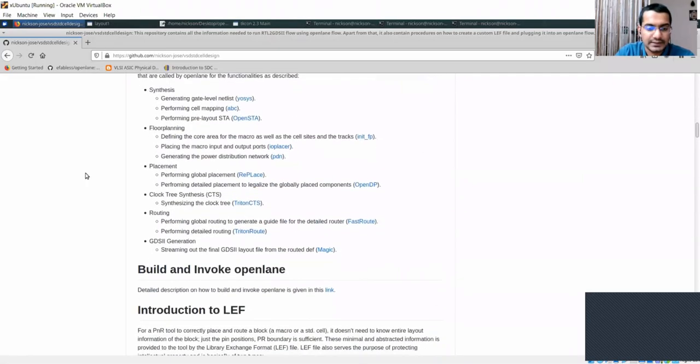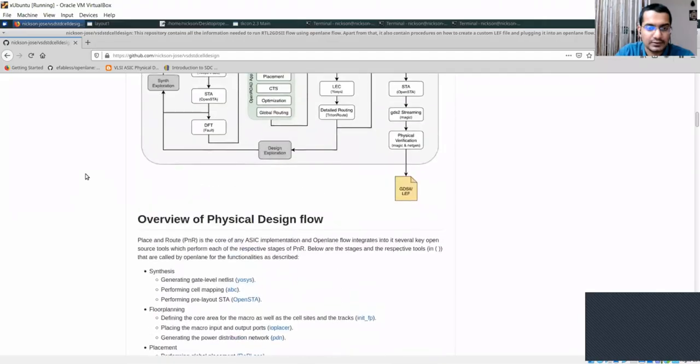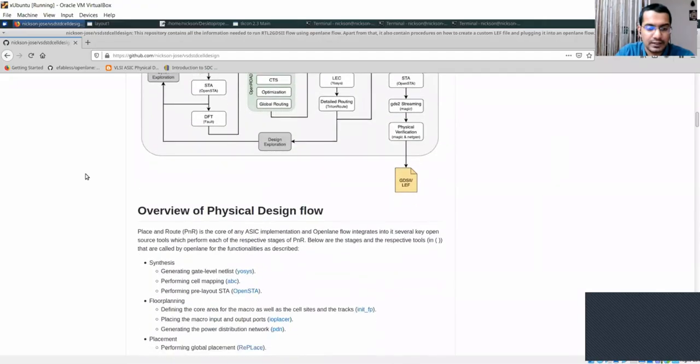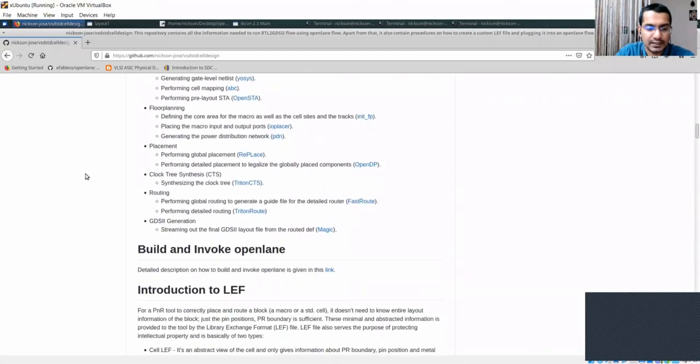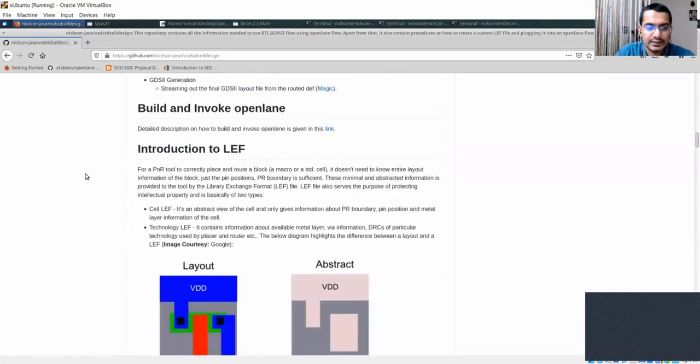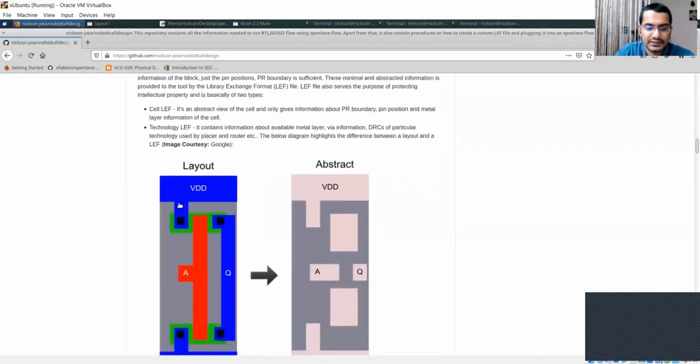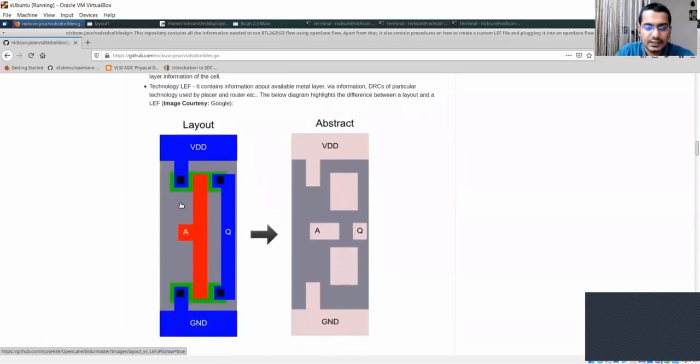Now the next step is to again take these metal levels to the higher level metal. Okay, let's see how we do it. The steps remain pretty simple. You deposit oxide, you deposit SiO2, the same thing that we did for this layer. You deposit SiO2 and you again do a chemical mechanical polishing over here. And the next step is again to pattern the same thing. I have not shown the patterning or the photolithography techniques over here, but we know that there is a mask 14.